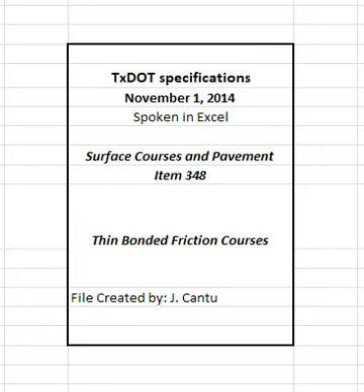2.1.1.1 Blending Class A and Class B aggregates. Class B aggregate meeting all other requirements in the table may first be blended with a Class A aggregate to meet requirements for Class A materials. However, Class B virgin, non-recycled, aggregate may be disallowed when shown on the plans.